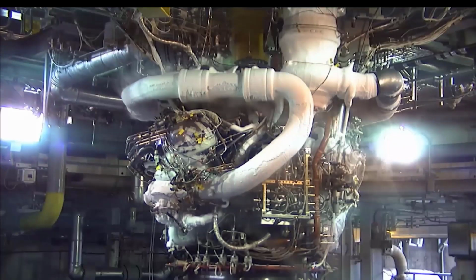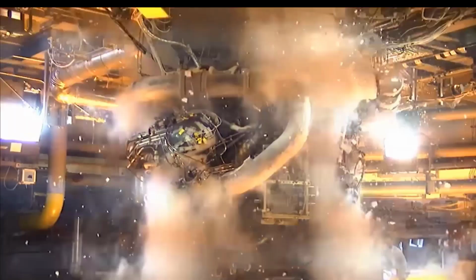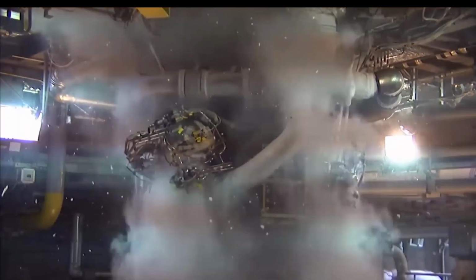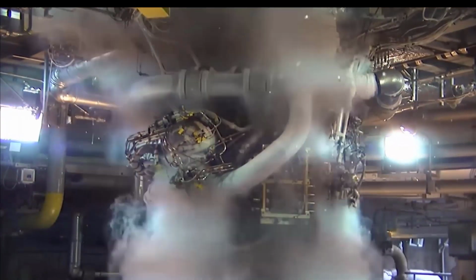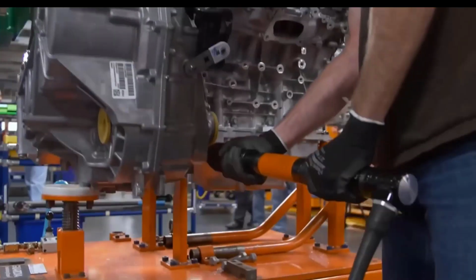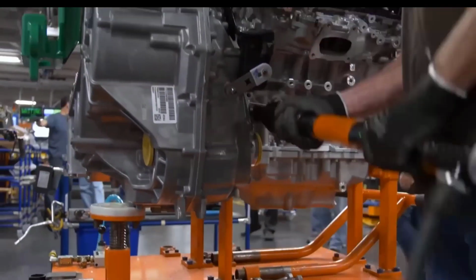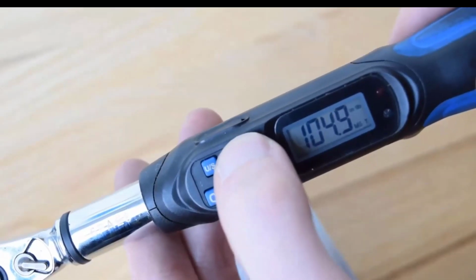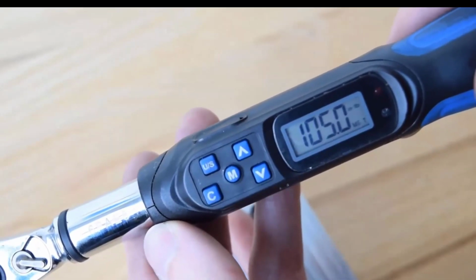In practice, vibration is the biggest problem for bolted connections in machines and vehicles, and without careful consideration, the machine will literally shake itself to pieces. Applying the proper preload goes a huge way in improving the resistance to vibration. The general guideline is to apply between 70 and 90% of the bolt's proof load as a preload for static joints. Preload is usually controlled by the applied torque.